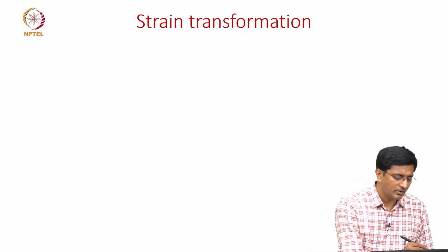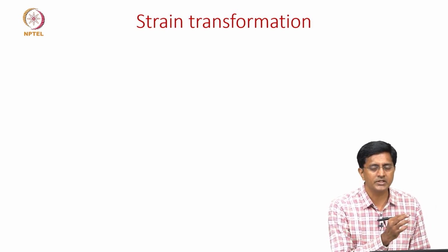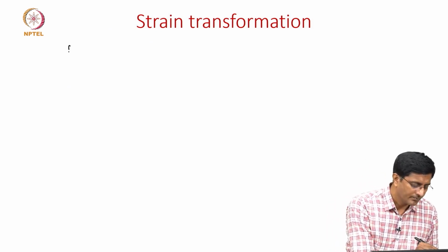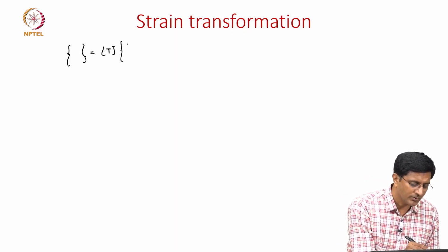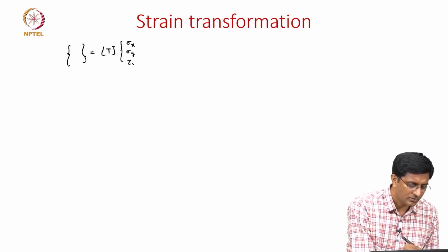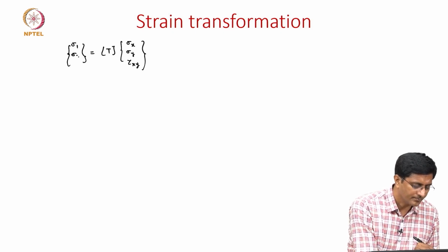So, we will see that similar to what we have learned for the stresses, we can also apply for the strains. Previously we were saying we can use this transformation matrix to go from the body coordinates to the material coordinates.